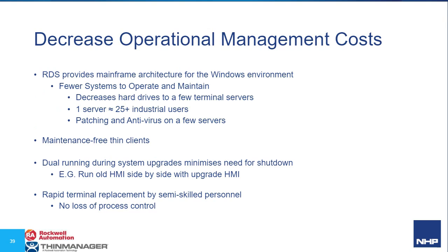But the big payback comes from the ongoing operational management. There's typically a lot fewer systems to operate and maintain. Instead of 25 or 50 computers out in the plant, I've just got a few servers in my server room. If I do need to patch things, instead of going to 50 computers individually where I'd have to put the patch on and possibly do it at a friendly time for the process if it needed a reboot, I just go to ThinManager and I select a server and I click a box to take it offline.